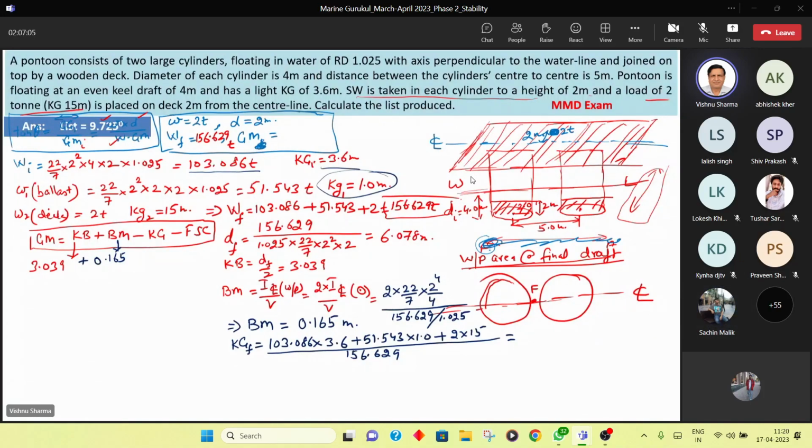This gives us KG in one step, because we cannot make KG itself a new question. It is 2.890 meters. So I put KG here as 2.890. Please review KG. If anybody has any doubts, let me know. Done, sir? Done up to this place?